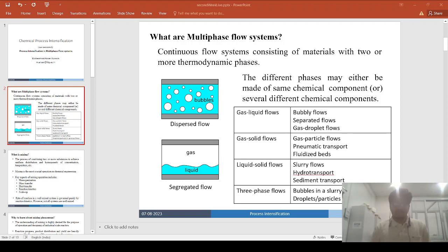The reactors that have a handling volume in the range of microliters, or their smallest dimension being less than or equal to 1000 microns or 1 mm, can be called a microreactor. Because of their small size, they are able to provide a very high surface area to volume ratio. Because of the increased surface area to volume ratio, their potential for providing rapid heat and mass transfer is very high.